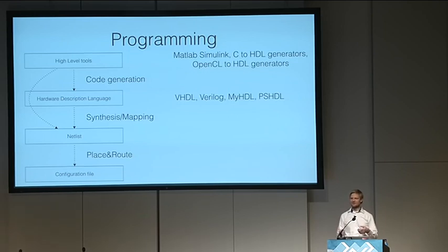And the seed is sometimes the checksum of the file, so sometimes if you're generating a file and you change the date in a comment, then you will get a different place and route result. There was a case where one vendor said, oh wait, the version that we created on the 26th works the best, because the comment was right and the CRC checksum led to the best seed, which resulted in the best place and route.